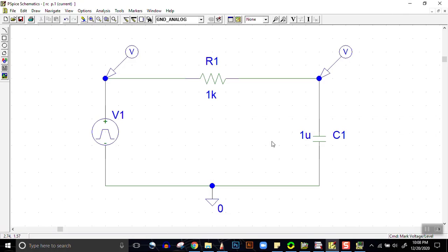Then you have R and C, so analytically you find the time constant RC, whatever that might be. You compare the 2 time constants, whether they are equal or not. They should be equal or very close to each other.